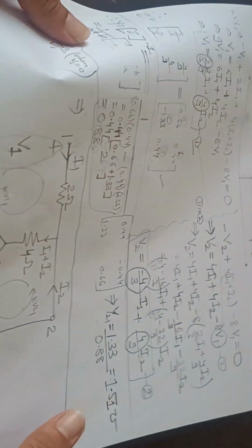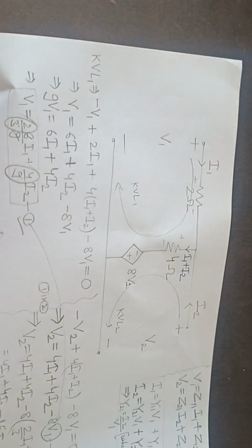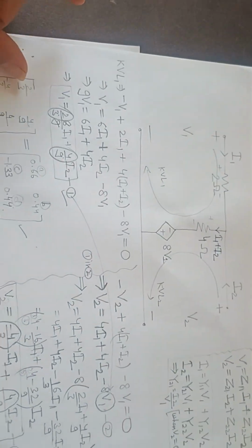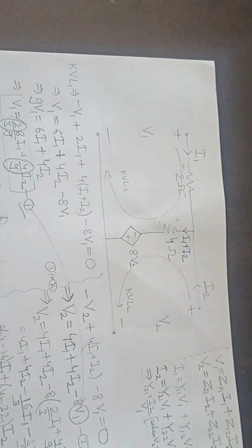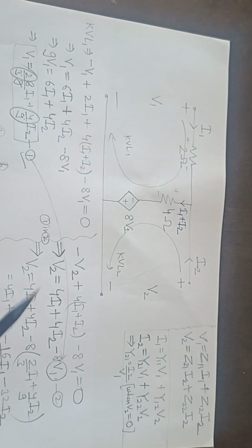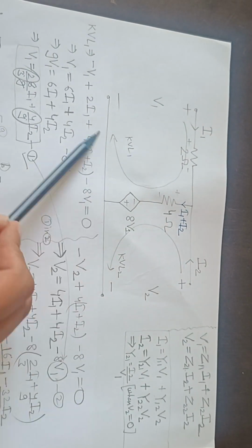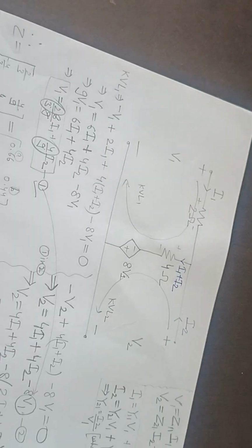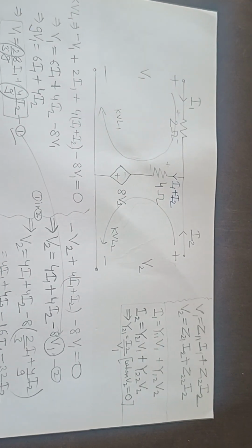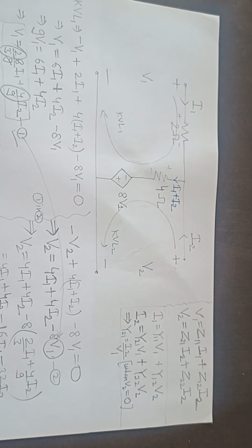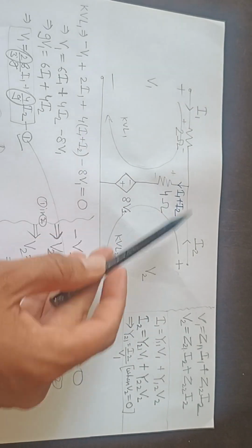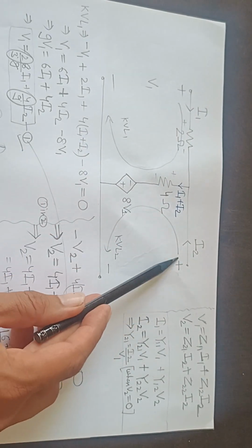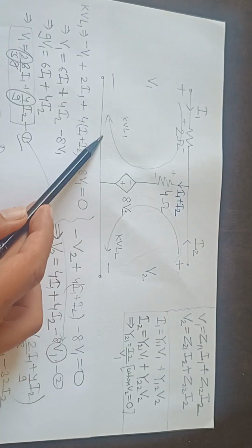Another way to solve this thing is like since it is a T network. Okay, so since it is a T network, another approach can be like, first we will find Z parameter, because for pi networks y parameter is easy. Okay, you just need to apply two KCLs at two nodes, and similarly for T networks Z parameter is easy because we just need to apply two KVLs.